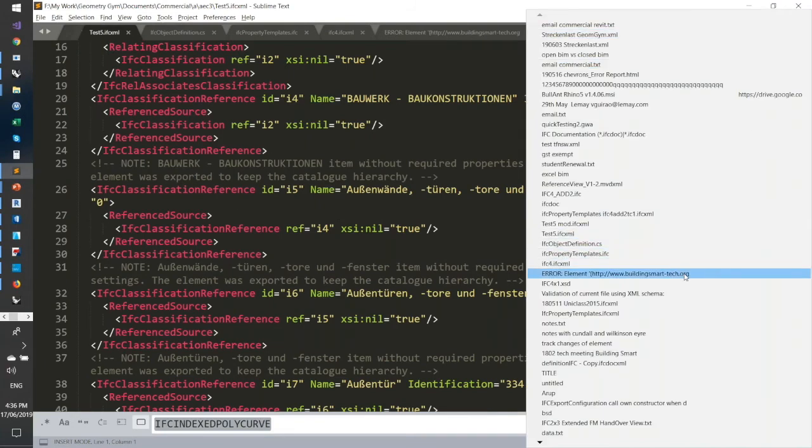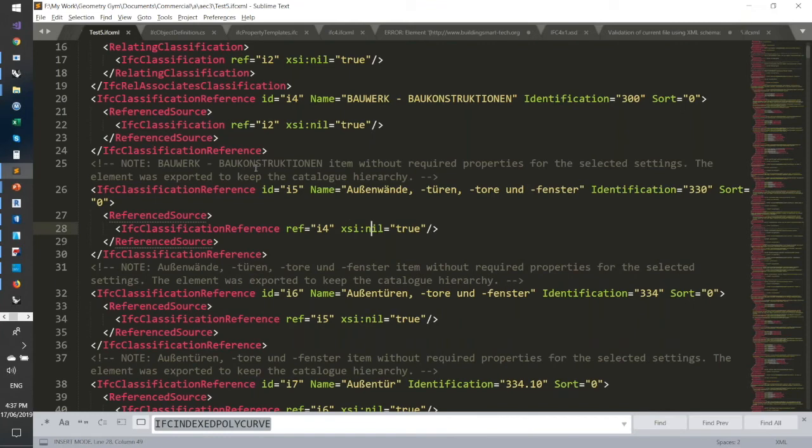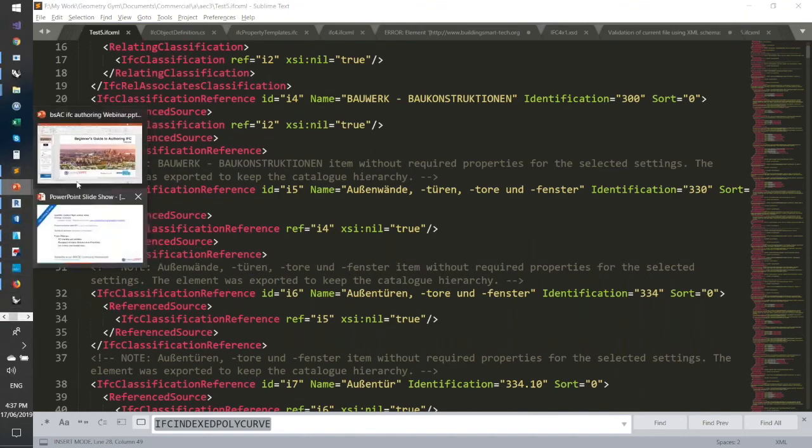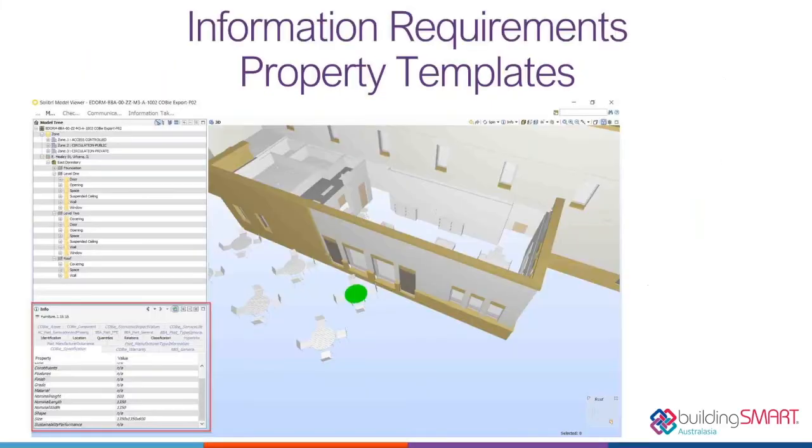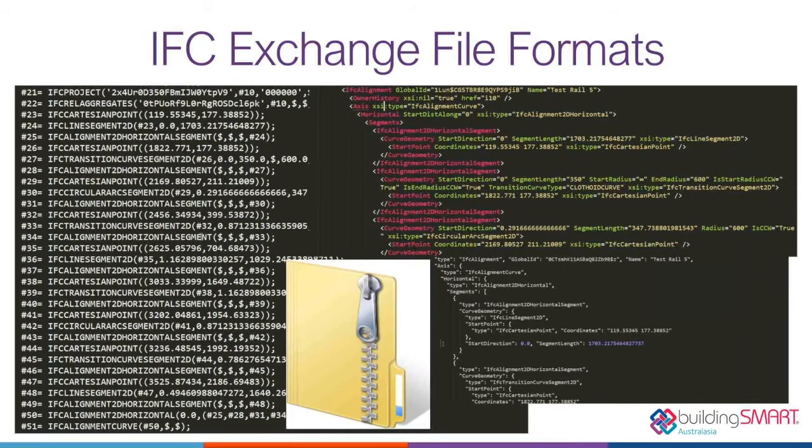this year. As it's a text file, if you're brave enough, you can actually open that IFC text file and edit the contents of it. That's not really a recommended workflow. It's easy to get an invalid IFC and change the wrong thing or not quite get the desired result. I think the most important thing is to add pressure or suggestions and requests to Autodesk that they should, the same as when you link in a DWG or a different file format, provide the option of a base point. I know that has been asked of them.